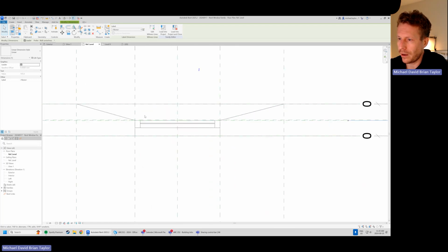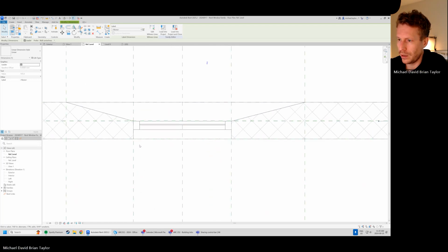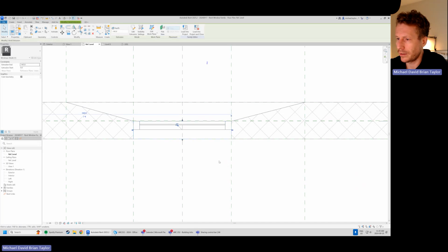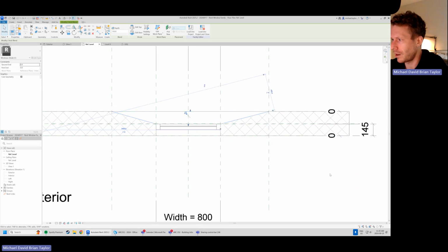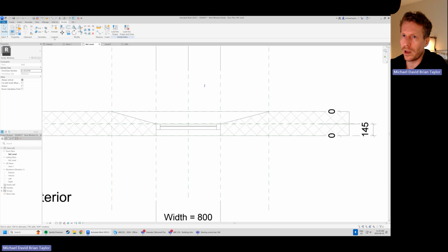But you will see that now that extrusion has changed dimension. Instead of 69 for the void, it's 145. The way that our blend is starting is actually a little bit different. Our void blend has now started further into the wall. It still ends at the same point, but that modification should help us update our family here. So I'm going to go ahead and save again.